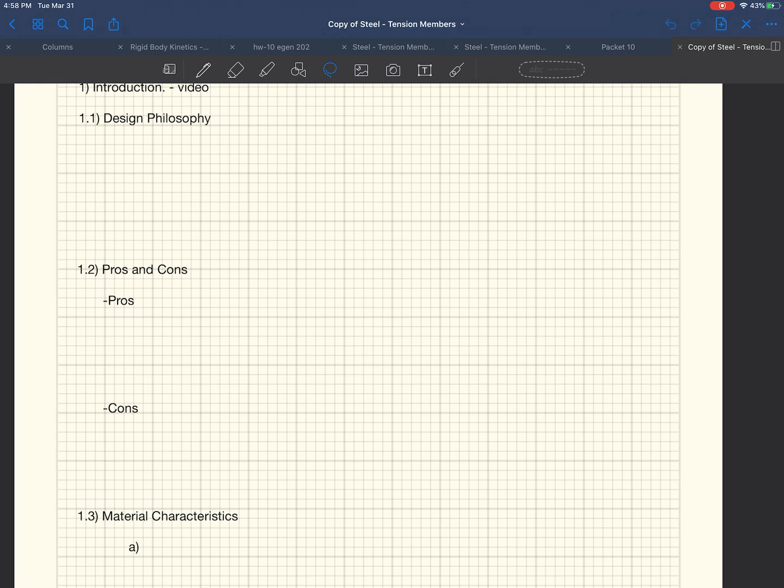They come out with this big giant bar. You can see it in the video. Then they heat that big giant bar up and roll it. That's how they get those shapes. They have these big rollers that go back and forth on those bars while it's still hot in the process. I think they're called hot rolled sections. The wheel rolls back and forth under lots of pressure, and that's how they get those wide flange shapes, channels, and angles. It's not like they're taking two separate parts and welding them together to get the I-beams. It's all one cohesive unit. They're not casting metal into a die that looks like a wide flange. They're just getting a big bar and rolling it into those different sections, right?